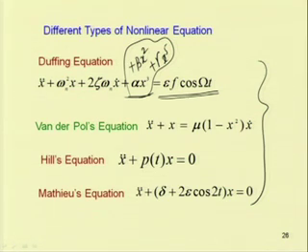So, this is the Duffing equation for free vibration by putting the forcing equal to 0; the Duffing equation for forced vibration can be written in this form. For forced vibration also we can have two variations. In this case we can have strong nonlinearity or weak nonlinearity. In case of weak nonlinearity we can remove this term epsilon and we can write the equation, so that is f cos omega t.